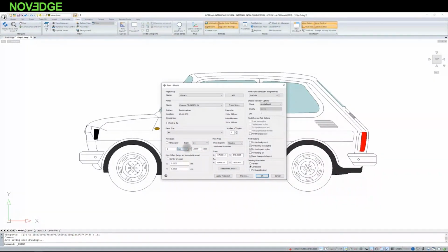I prefer to convert to millimeters, and now when it comes to the scale of the printout, of course it can't be 1:1, because I absolutely won't fit it on an A4 format. First, let's try a scale of 1:50. And here, for now, I entered 1:50 because I want to have this fragment for the drawing in such a